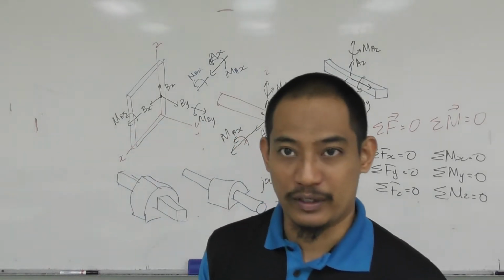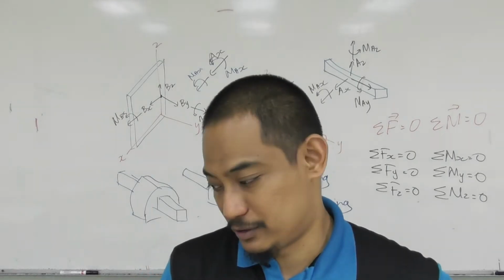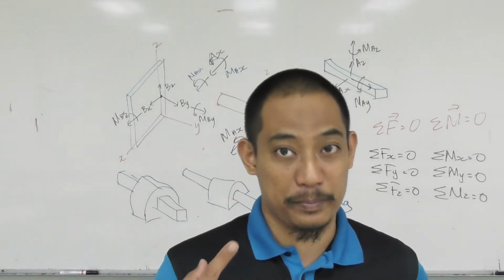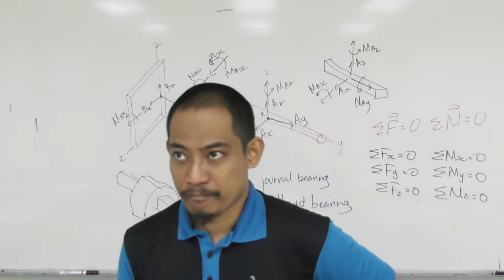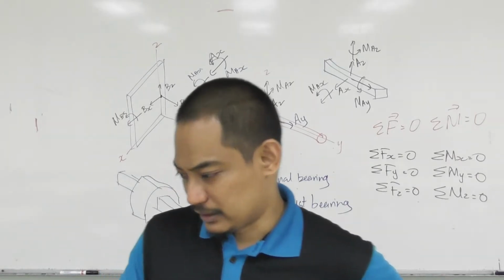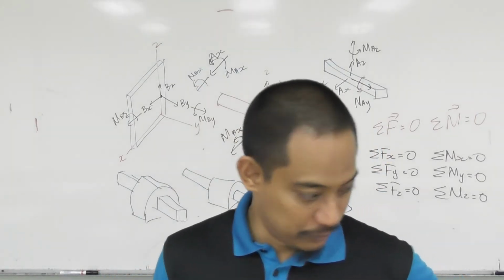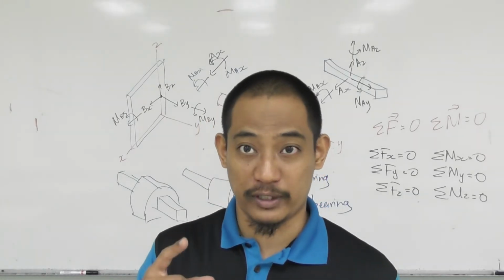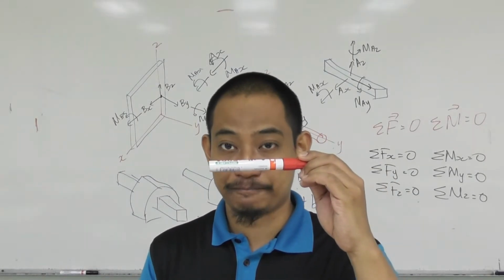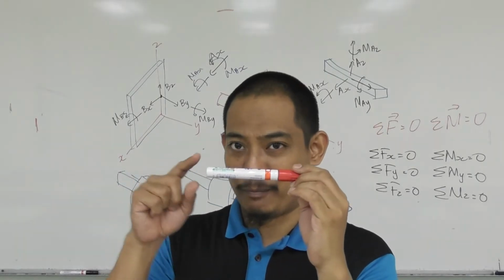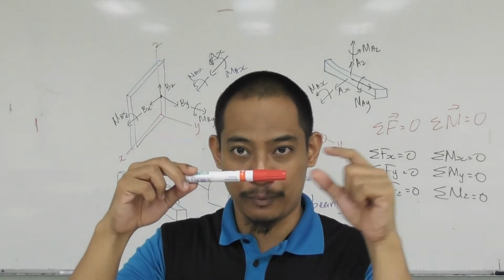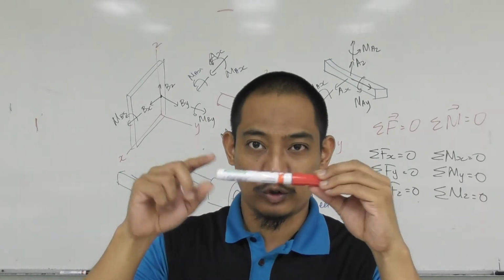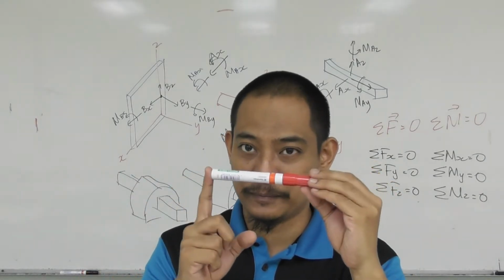Improper constraint. This is another concept, improper constraint, meaning that the constraint is not proper. Right now, I think the example gives you two ball and sockets. If you have this structure here, with a ball and socket here and a ball and socket here, how many unknowns here? 3.